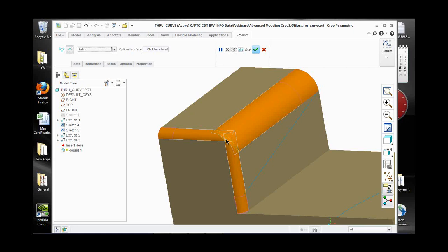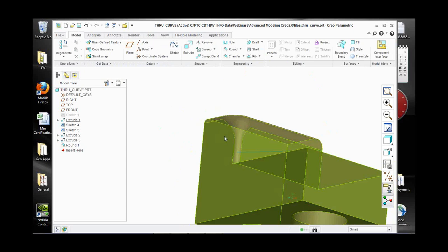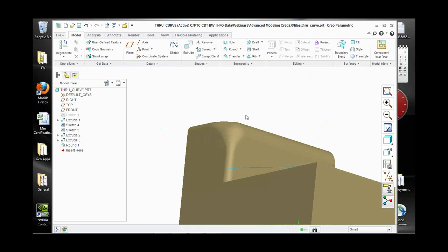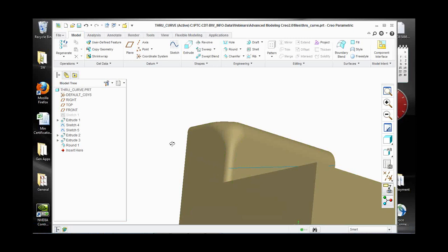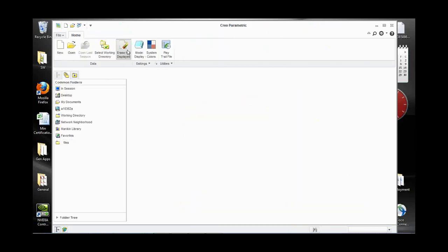Now, the only way you can really get this to work is if you're using this within the multiple set. Because you're in multiple sets and you're in one feature, it can see all of the interactions between the rounds within that one feature and give you the ability to manipulate those as transitions, okay? So transitions, I'll say again I want the corner sphere, and then there is that result, okay? So it is the converging of multiple radius values all into one corner. You can do that and handle that out of transitions, all right? All right, I got to keep pushing along here. We're already taking too much time.